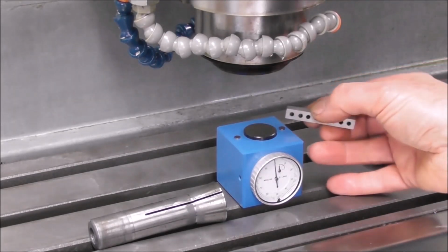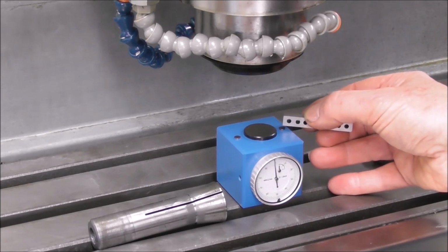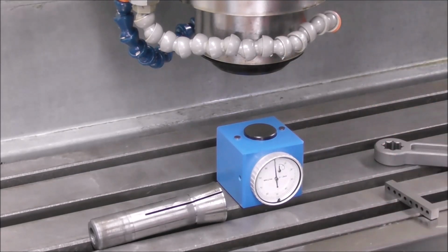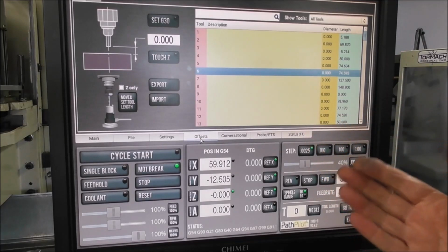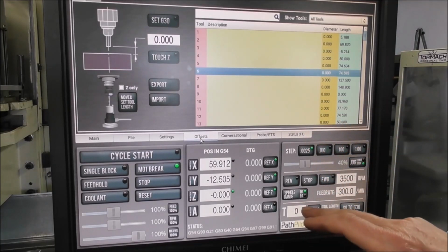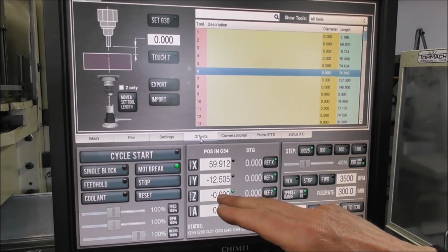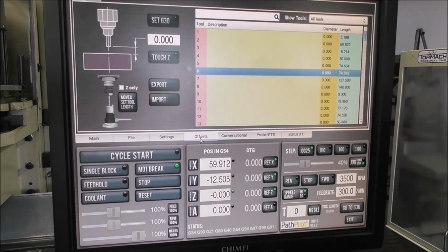And so now we can use those buttons also, for example, for setting your probe and getting the two talking the same language as regards to Z height positions. So setting up the probe to the same Z position language, remember we've just set the tool setter by putting a tool 0 in there and touching it down with the 0 on the dial indicator setter and zeroing the Z DRO. So this is the tool setting position.